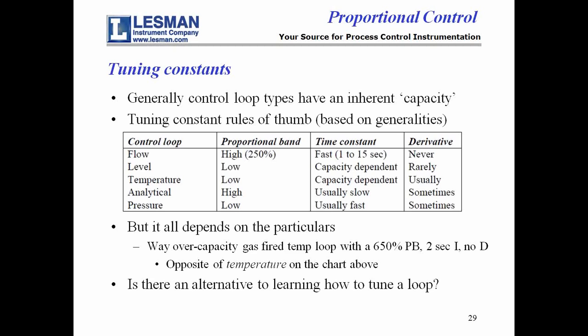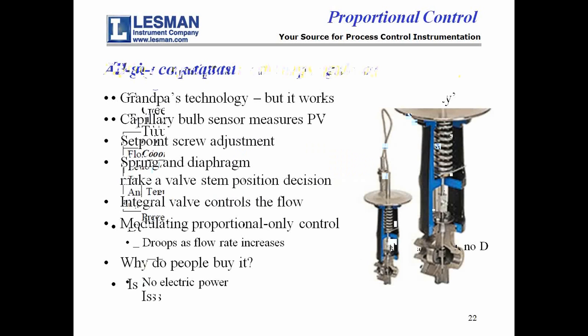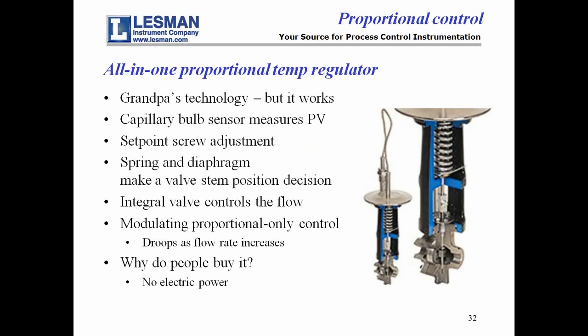Well, at one extreme end, there's the all-in-one proportional temperature regulator. This is actually Grandpa's technology, but it works. You can see here there's a capillary with a bulb on it, and that is a sensor into the process. There's a screw adjustment on here for the set point adjustment. There's a spring in here and a diaphragm. So all this works together to actually give you proportional modulating control through the valve at the bottom down here.